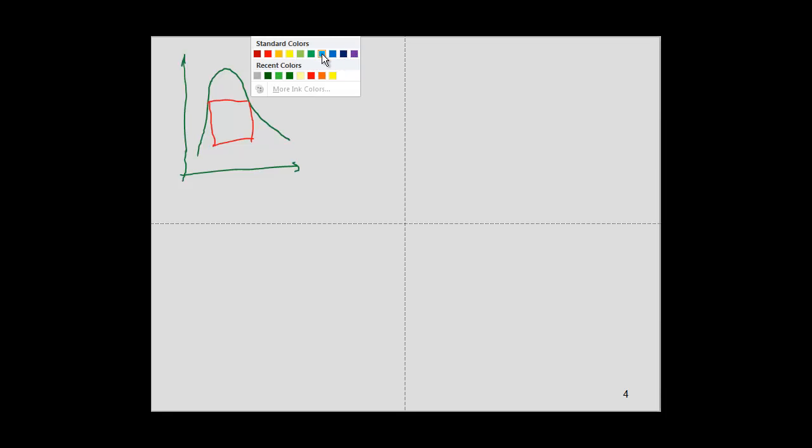We're going to introduce this blue one, and we're going to extend it until the point we get saturation, right? So we know that we can extend this line here. This will be my saturation line, and then I will have my isentropic compression. I will do the same here. I will try to accommodate until we get saturation. And this is almost our TS diagram for refrigeration.